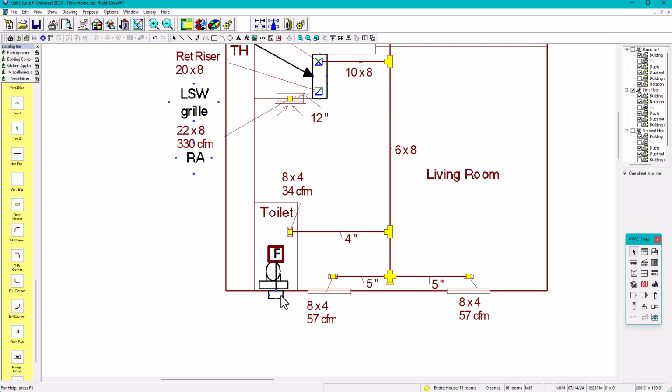So this wall cap actually usually has a screen, it has a backdraft damper, because if this wall cap doesn't have any protection, all the bugs or air or humidity, everything is going to go through here, right? So we don't want that. So that's why they have protection, like a screen or a backdraft damper. That's very important. And the manufacturer already provides you with that. Also, if you Google it, there are so many options for backdraft dampers. We're gonna do code analysis maybe in the next video. Maybe I'm gonna make one more video about code analysis, because this is just final touch-ups.